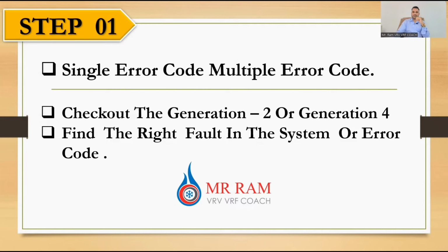After that, we have to know the project generation, second generation or fourth generation. Because the second generation has different kinds of projects, different push button settings, and different mechanical parts in the outdoor units of the VRF system. So we have to know first whether it is the second series or the fourth series. How can we identify it? We can identify it from the series of the units, like Multi V 2 in the LG system, or VRV 3 from the Daikin company. So dear friends, you can go for troubleshooting any project.